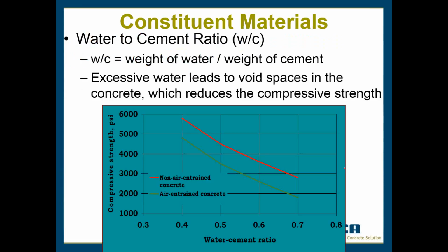And there's one more slide. It shows up really dark on my screen. Hopefully you guys can see it. If not, just let me know. But again, we're just showing here how using excessive amounts of water, you can see down here as the water to cement ratio increases, the strength just dramatically drops.